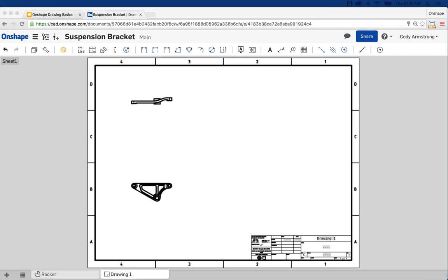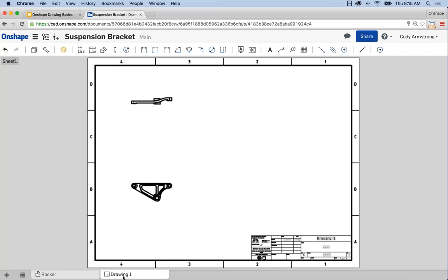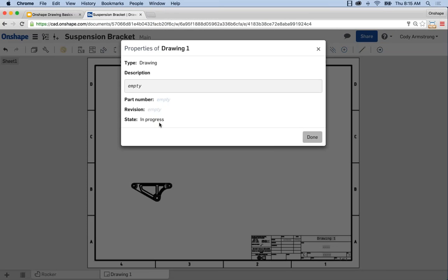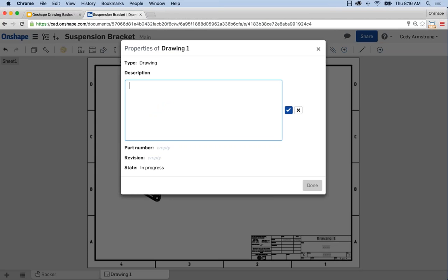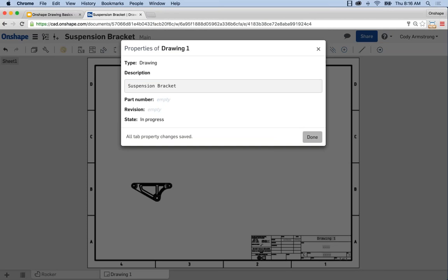Question. Properties stored with the sheet size. There are properties associated with a drawing, and this is a bit of a tangent, but it's worth pointing out here. Things like the title block and filling out all this information, there are linked values that you can go in and enter. So I can add a description, for instance, to the drawing and have it populate this title block. I can add metadata to the actual drawing and have it populate. So just keep that in mind.